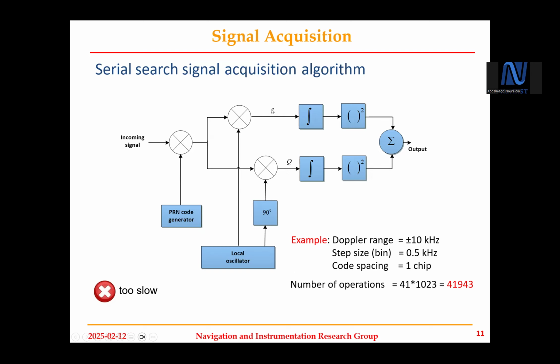So you need to keep the maximum power in the in phase stream. How you measure that, you will see later, there is something called a discriminator. It tells you how much power you are getting in each. If the power is higher here, for example 50%, then you need to shift the phase by a certain amount so that you maximize power on I. I believe you will get it shortly in some of the coming slides.